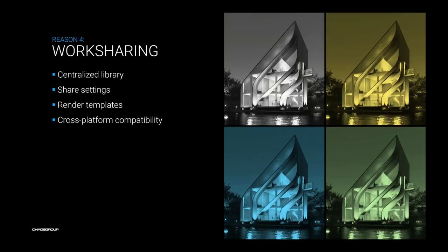Reason 4, V-Ray for Revit allows for sharing easily what you've done with your colleagues. Please don't mistake it with Revit's worksharing, and don't expect that every time when you click Sync to Central, you will send your V-Ray settings to the other team members. V-Ray for Revit does not work like this.